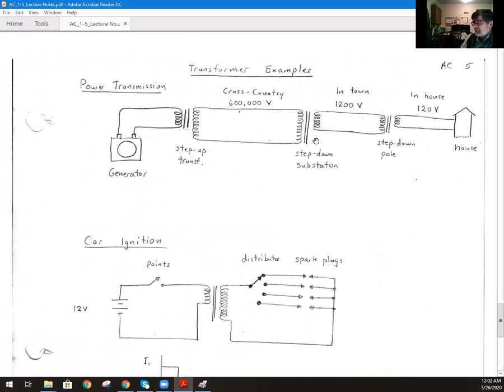Then as you approach that city, somewhere near the outskirts, you have a substation, and there's a great big step-down transformer. And from that, the output, this doesn't show, there are usually more steps than just this many, but it's stepped down to a smaller voltage and spread out to a whole bunch of different wires. So there might be 10 different distribution lines running at this level.